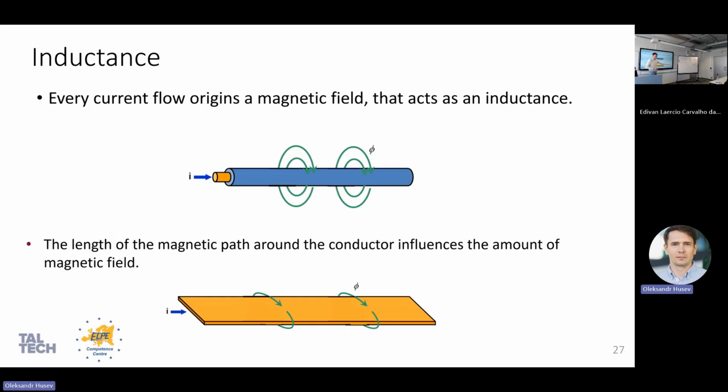But if you apply Ampere's law, in that case I can compare something like this. If you have this shape and then you smash this shape, and the current is equally distributed, just imagine that we have even constant current, don't think about the skin effects a lot. In this case, if you apply Ampere's law, you will see that the inductance, the total magnetic flux created by this somehow distributed current, is lower, because at these points they compensate each other.